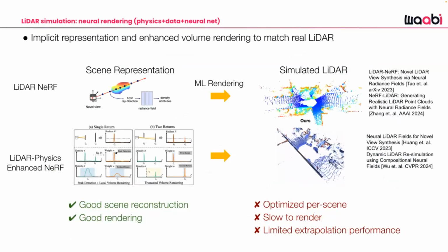And then there are a couple of works available for neural radiance field approaches that are specifically optimized for LiDAR sensors. For example, there's Neural LiDAR Fields, NFL, that specifically tries to model an active sensor and accounts for some of the effects you might see with LiDAR data, such as beam divergence and multi-echo returns, like dual returns. If you send a beam of light, you might get two response peaks that you want to send back as points to the sensor.